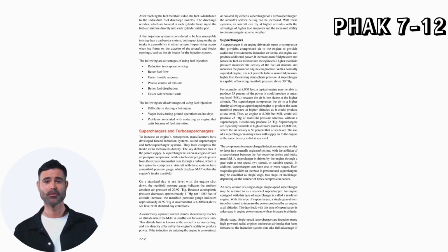An early version of a single-stage, single-speed supercharger may be referred to as a sea-level supercharger. An engine equipped with this type of supercharger is called a sea-level engine. With this type of supercharger, a single gear-driven impeller is used to increase the power produced by an engine at all altitudes. The drawback with this type of supercharger is a decrease in engine power output with an increase in altitude.